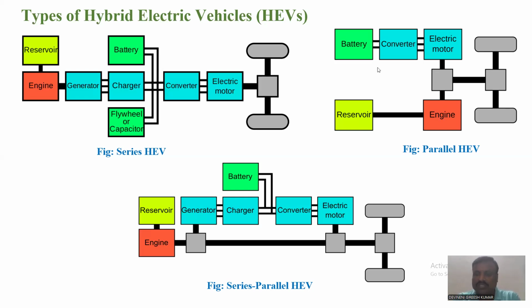And also the charging, how the battery charging will take place here, because it's not self-charging here also. So whenever the energy is there in the battery, the electric motor is driven by the battery so that it drives the wheels. If the energy is lost in the battery, so if it is completely discharged, then the engine solely drives the electric vehicle wheels. Also, it drives the shaft of this particular electric motor, which is directly connected to the engine and electric motor, so that this motor is also driven by this particular engine along with the driving wheels of the EV.